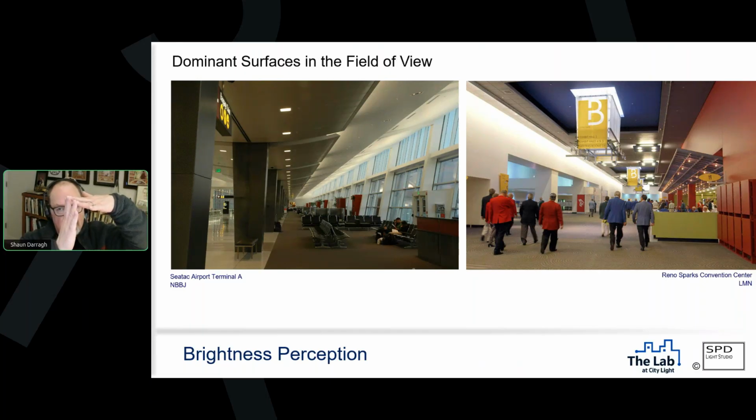So we have light gently washing up that surface so that it doesn't go dark by comparison to the window wall, right? Now, coincidentally, at night when that window wall is relatively dark, that light also then bounces down onto the structure of the window wall. So that becomes the dominant visual surface there, so that it doesn't go completely dark. Right? I hope that makes sense. It's a different experience at night, but it's intentionally still trying to maintain that feeling of relative brightness without using an enormous amount of power.